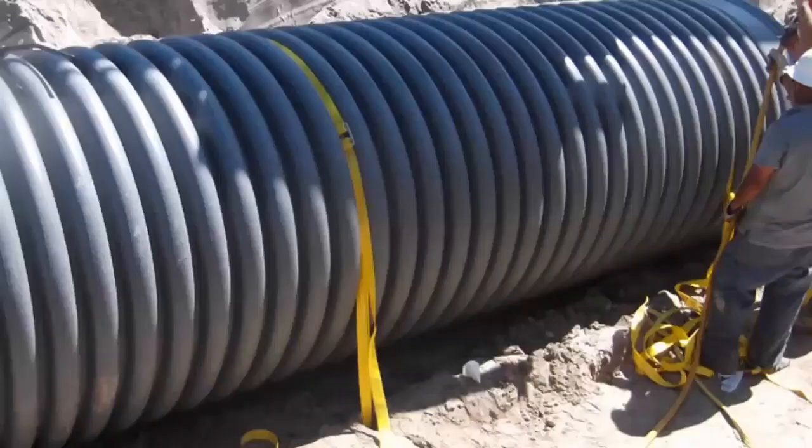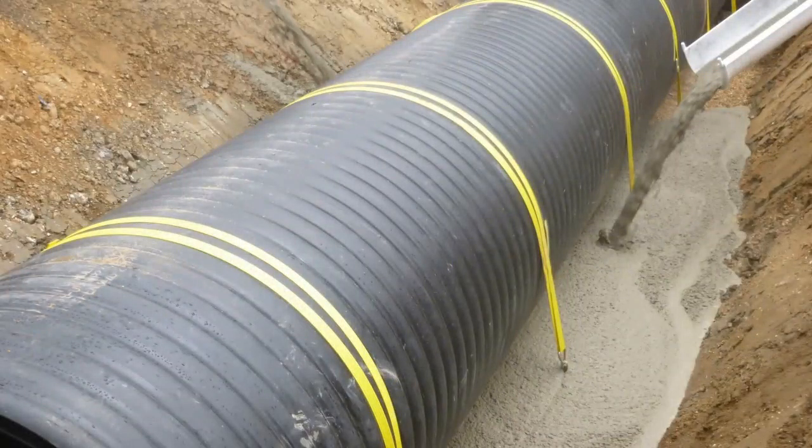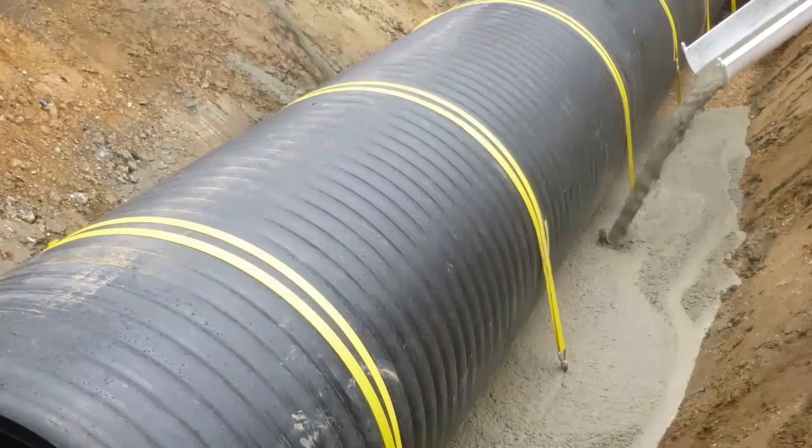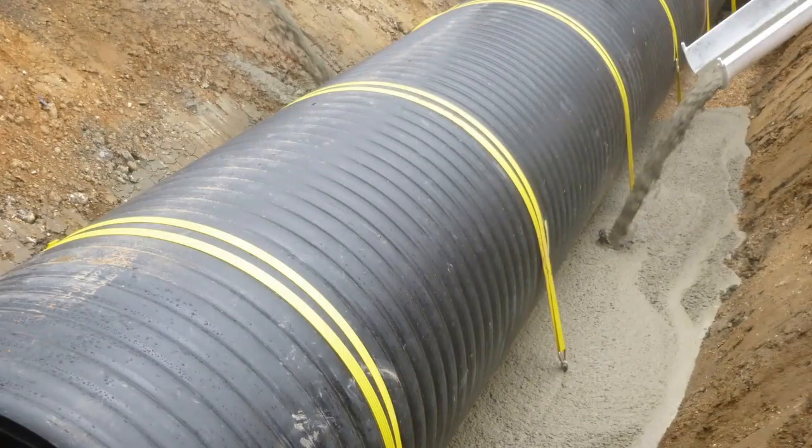So some options you have are tie downs, using tie downs there to tie the pipe down and anchor it into the foundation so that it doesn't float on you, especially if you're using a flowable fill, like a concrete mixture to backfill the pipe, some type of flowable fill that really has a tendency to float a pipe. So you want to make sure that it's anchored in correctly so that as you backfill and you're coming up with that flowable fill, it's not lifting that pipe up as it goes, because the density of flexible pipe is less than the density of that material that you're putting in there. So keep that in mind.